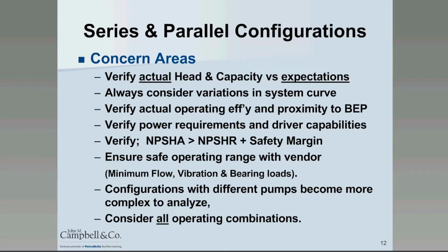It's also important to look at configurations where you have different pumps. So we have simplified the analysis here, no doubt, and used 2 identical pumps. And I'm sure there's many of you out there running pumps with different size impellers or different makes even, and trying to bring those charts together becomes more and more complex. There's different ways of doing that, and I've built spreadsheets in Excel, replotted pump curves, that kind of thing, in order to make that analysis, but it definitely gets a bit more complex. My guidance there would be to work closely with your pump vendor in that analysis. And then finally, do consider all operating combinations.